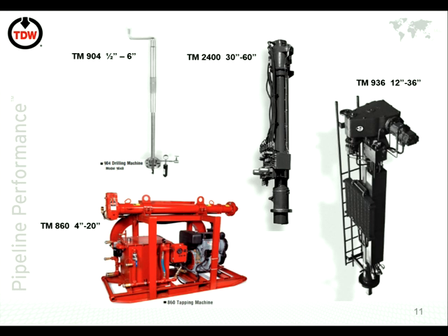Are there challenges actually with concrete pipelines, like breaking off the concrete? Not really, because the cutter you use will cut the concrete very cleanly. And generally speaking, if it's a pressurized pipeline of concrete, the concrete is in good quality, so it generally won't break away.